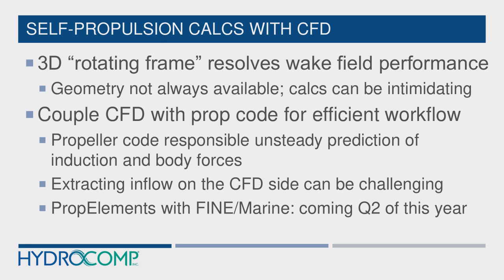That's something that prop elements can generate, a propeller, after or even prior to the wake adapted calculations, to develop a proxy propeller that can be put on the CFD calculations, much like a model tank would do with pulling a stock propeller off the wall and putting it on a model for self-propulsion analysis.